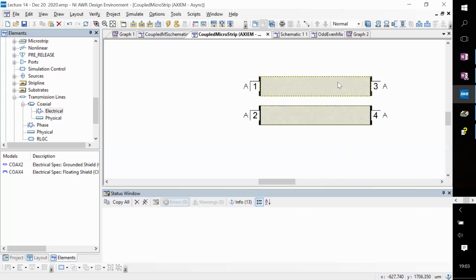Okay. So, in order for these set of properties which I explained, that if I send a signal on 1, 99% should go here, 1% should go here, and 0% here, some conditions need to be satisfied for the length of the coupler, and the even and the odd mode impedance of the coupler. And that's what is described when you look at the math behind the coupler design. Okay. So just any coupled transmission line of this type will not do the job you're trying to. You have to choose the parameters correctly.